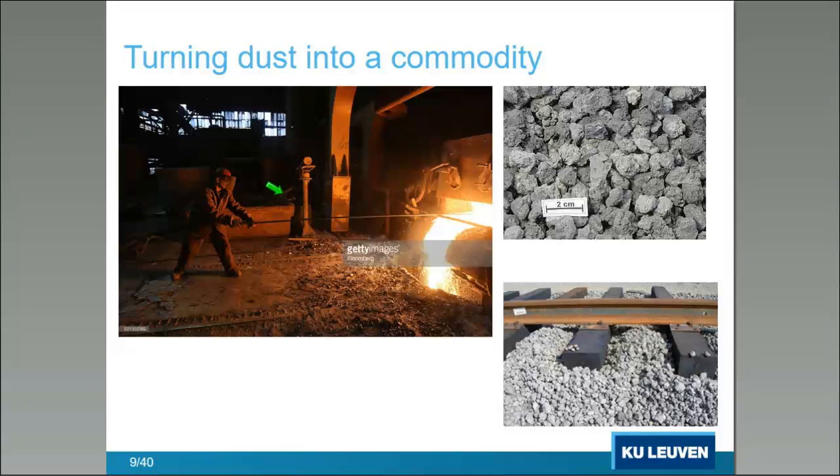So here, indeed, a picture of the slag. So this is, the slag is floating on the top of the melting bath. Here you see an operator who is pulling out the slag, because this slag can be used as a construction material. So this is solidified slag coming out as a byproduct of the electric arc furnace.